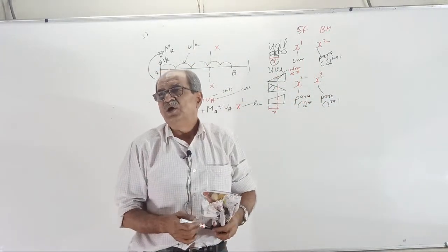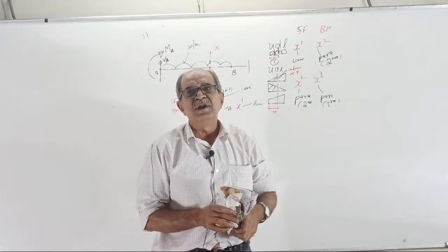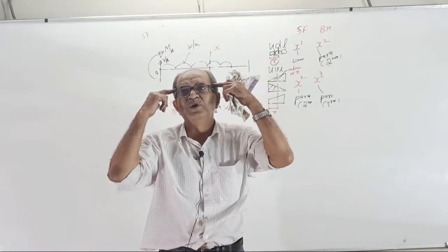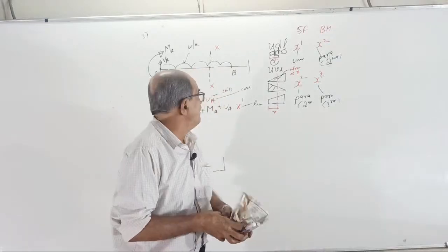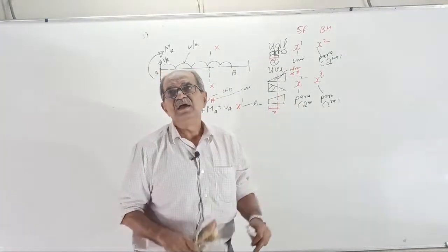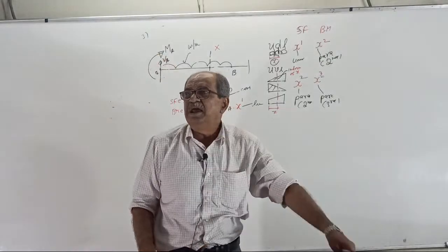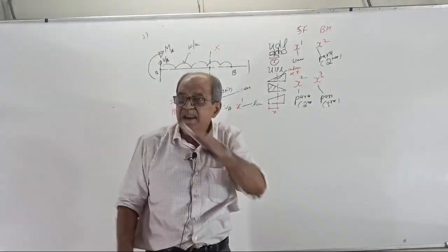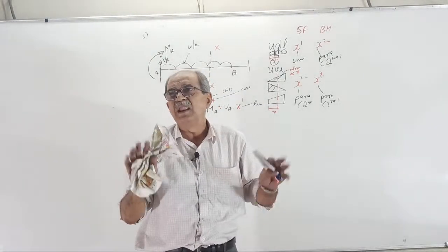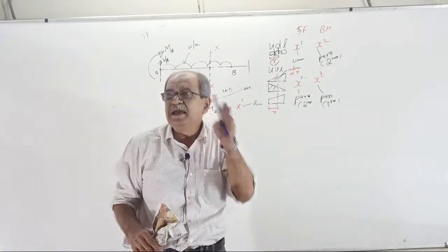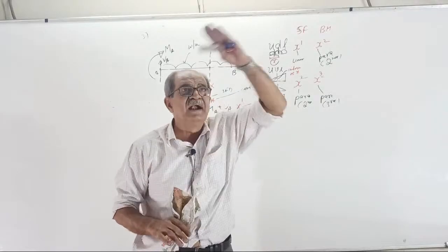Fully clear? I don't require all these things here. In the mind it should come. UDL, last I am telling, I am rubbing everything now. UDL, shear force linear, BM second degree parabola. UVL, shear force second degree parabola, BM third degree parabola.